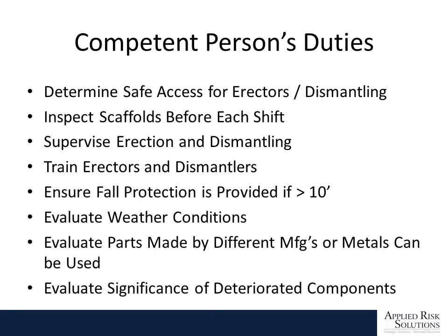The competent person determines safe access for erectors and dismantlers. They inspect the scaffolding before each shift. They supervise the erection and dismantling, they train erectors and dismantlers. They ensure fall protection is provided if greater than 10 feet.